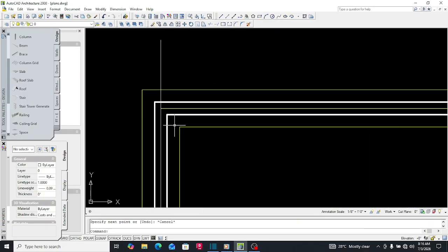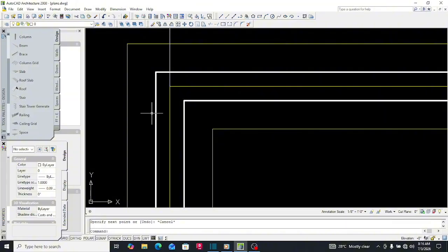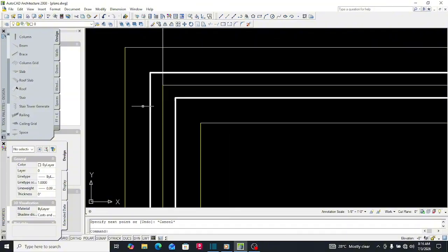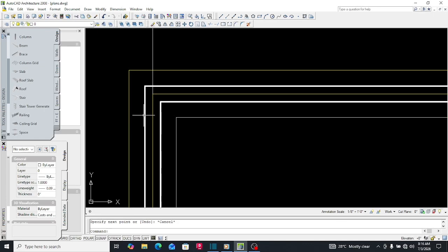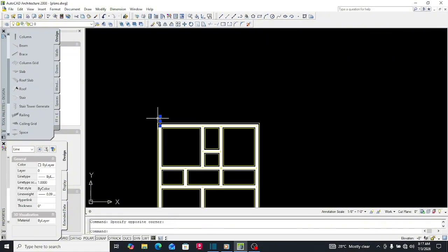The reason why they make the trenches so big is to create some comfort for the mason. If they dug the hole just as the measurement of the block is, fixing the block inside the trenches would be very, very difficult. Rather, they have to make it so big. Then when they are doing the filling, they can fill the sand somewhere here, somewhere there. Then it fits, or stands the blocks in place. That is it.